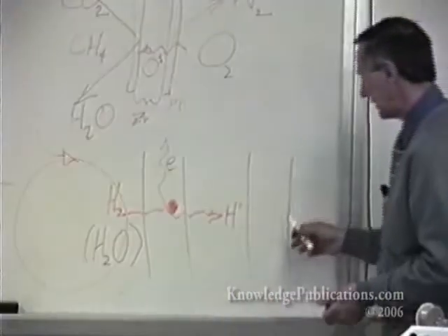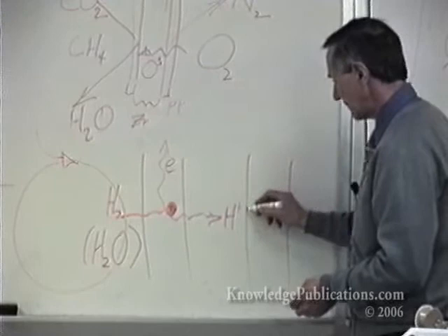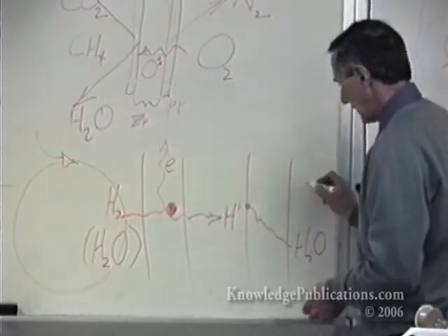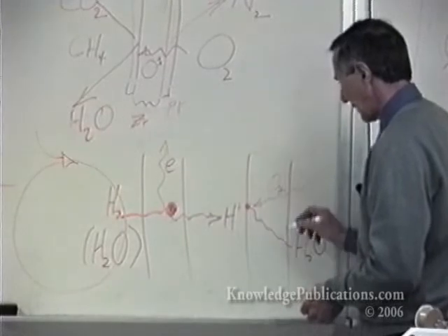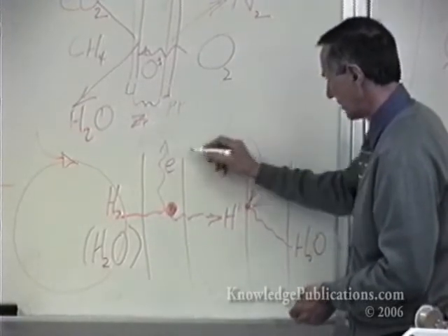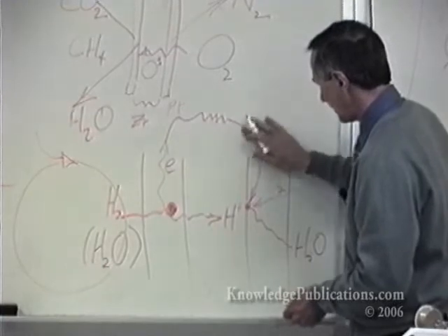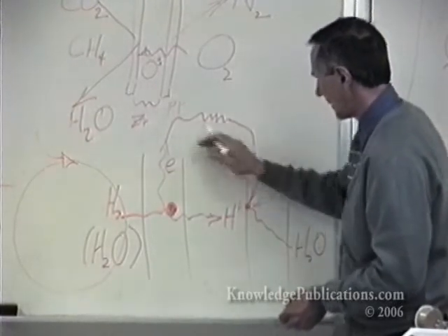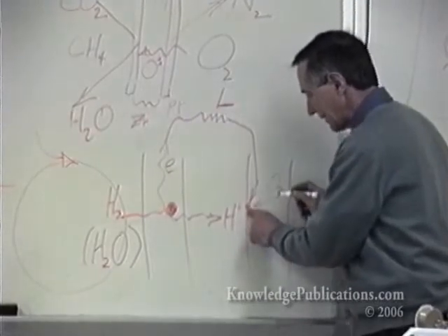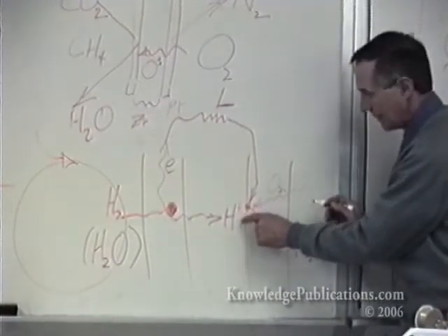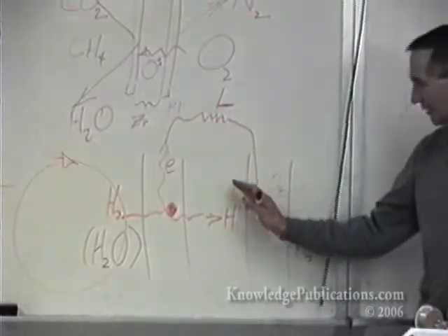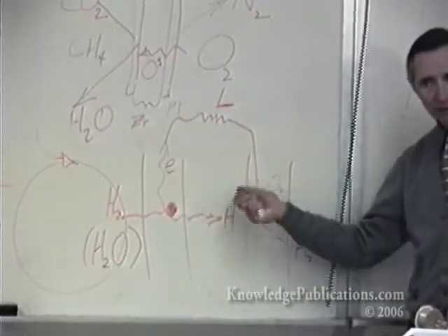Same way with the other side, you need conditioning that goes on the other electrode. This one is producing water as it reacts oxygen with the arriving hydrogen ions in the membrane, and adds them to electrons that are coming from the external circuit. So what we have here is the load that we've applied. The electrons come over and must come to a place where they can find oxygen and this arriving ion. And why that's very important is that if it just builds water up here, it'll block the oxygen or block the arriving ion.